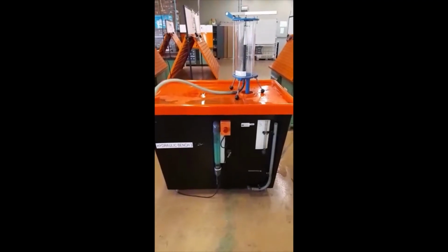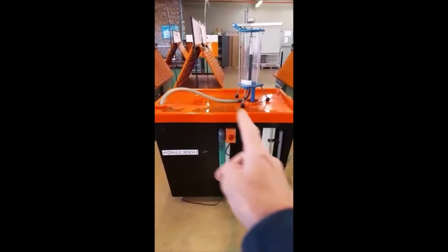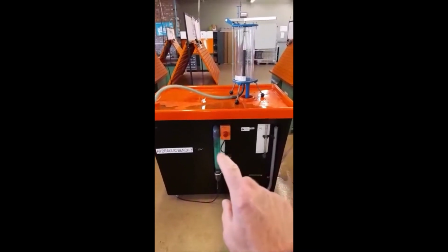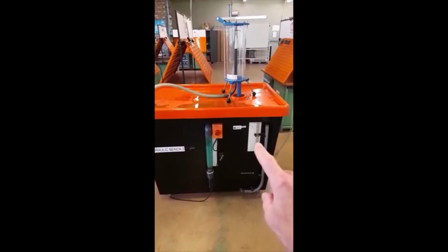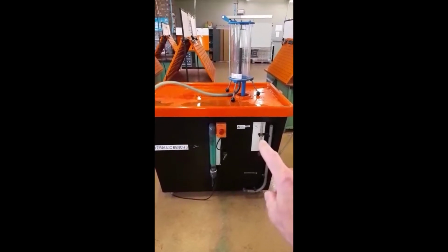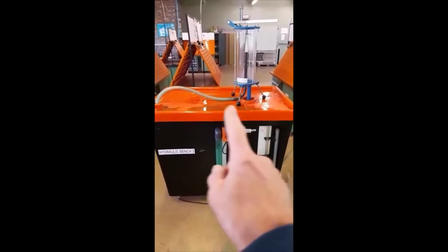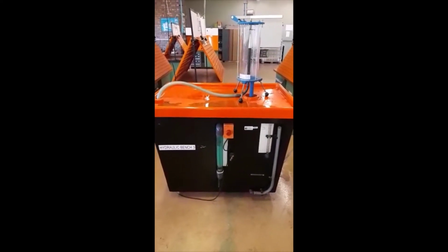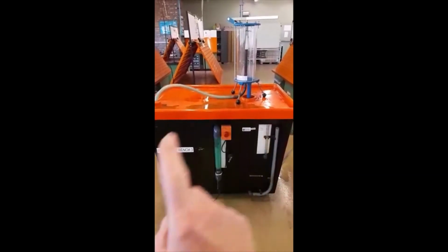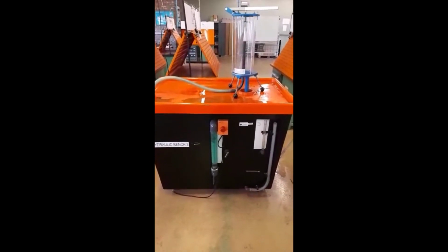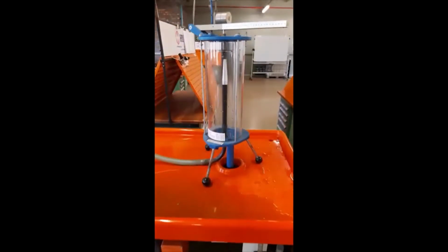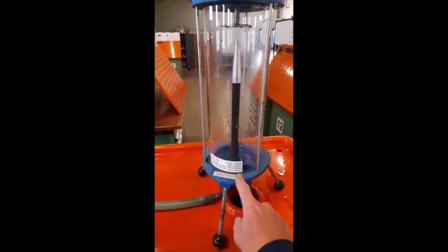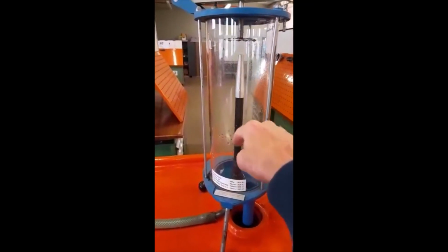The equipment we're going to use for this experiment, again, we're going to make use of the hydraulic workbench with the rotameter over here. There's the stop and start. And then we have the side glass over here, which we use to measure the actual flow through the system. You can refer back to the video of the rotameter lab for all the details about how the hydraulic workbench works. Then we attach the jet force apparatus to the workbench. Here is the inlet, and that of course is the jet.